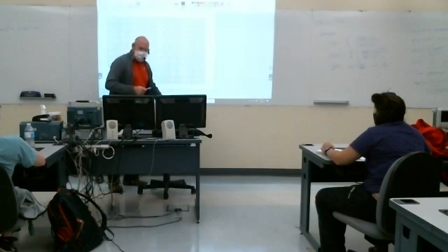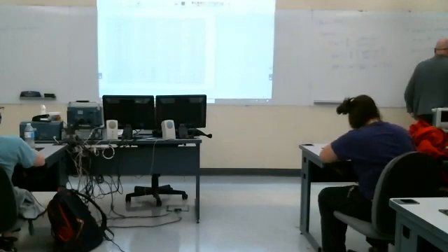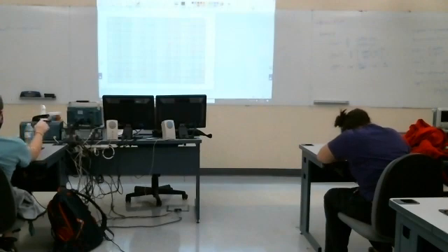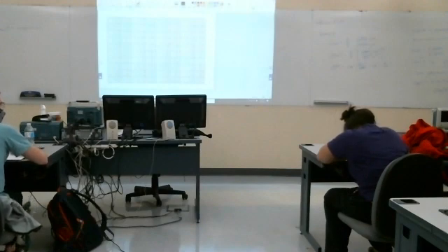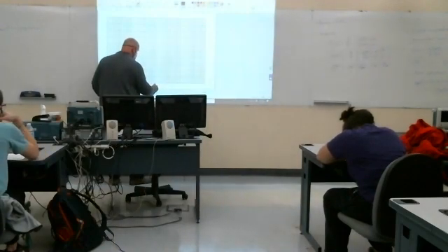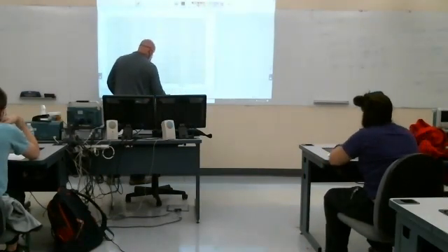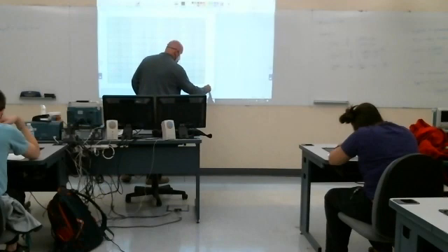Now, what we need to do is identify our critical frequencies and try to set up the scale so that all these critical frequencies are somewhere near the middle of the graph. So our critical frequencies are 1,000 and 8,000. So I'm going to just label this one to be 1,000. Okay. So this would be 10,000. This would be 100 actually. This would be 100,000.